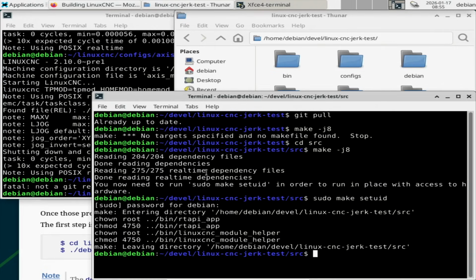Once you close this folder, your run in place is deconstructed, so it's no longer hooked up. So you need to leave this folder open. I used to run in place on production machines, and I used to just leave this folder open, always start LinuxCNC from this folder, and then if I needed to, I'd close it and do something else.